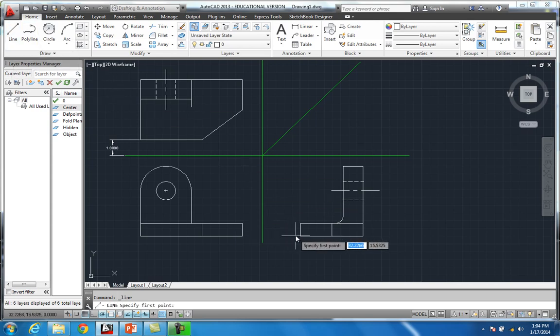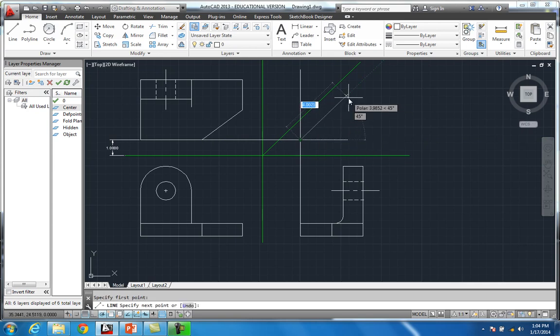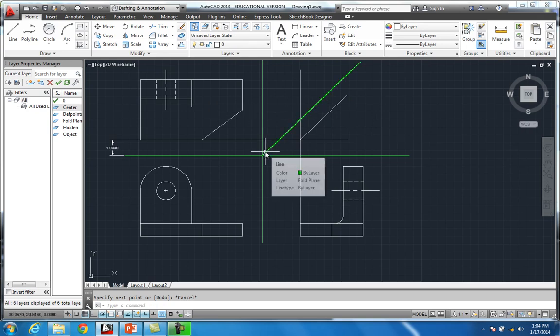But this was okay. You could actually just put that line straight off of that, and then put this line straight over, and then put a 45-degree miter line in, right? And then everything would hit that and come down, and your views would be perfect. I mean, everything will be lined up.